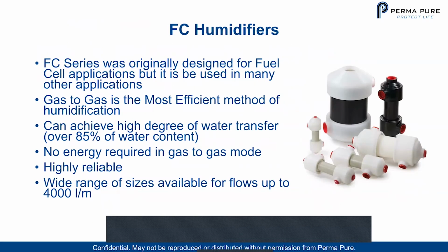So our FC series humidifiers were primarily designed for fuel cell applications, but they're used in many other applications. And they're designed for gas-to-gas humidification. We can achieve a high degree of water transfer, up to 85% of the water content in the gas-to-gas mode. In the gas-to-gas mode, no energy is required. It is highly reliable, and there's a wide range of sizes available for flows up to 4,000 liters per minute.